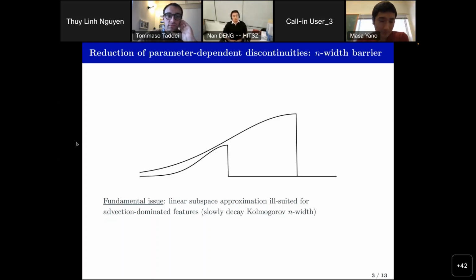The idea is that we would like to use that information to predict something right in the middle. If we do POD or any kind of linear approximation that takes linear combinations of those snapshots, really the best you can do is some sort of staircase approximation to the shock, which is not going to get you very accurate quantities of interest. You're going to be lucky to even stably converge these, because these oscillations can cause CFD codes all kinds of havoc. They can crash, and all sorts of other issues arise from solutions like this. That's apart from the fact that these are obviously horribly inaccurate solutions, and that's not really acceptable for our purposes.